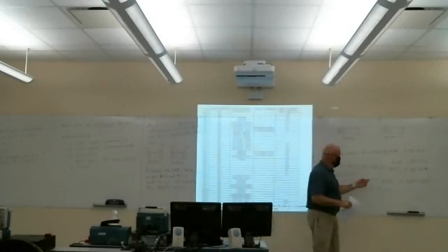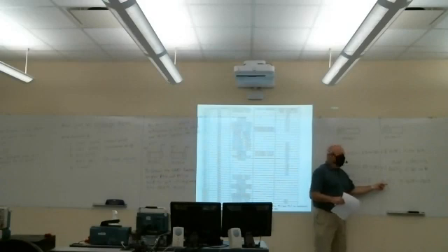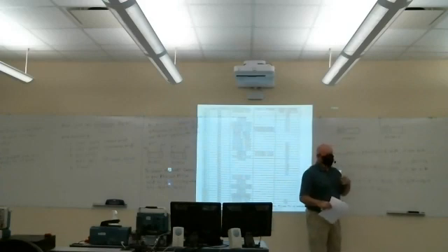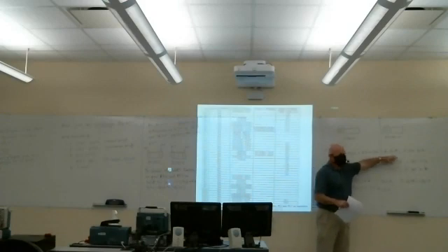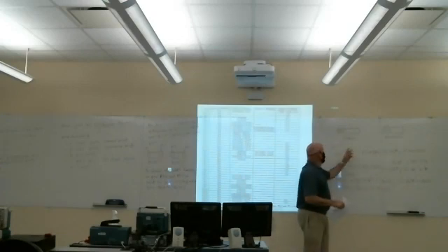So this would take the 1, 1, followed by 6 zeros and convert to 0, 0 followed by 6 ones, which is what 3F is. So not C0 is exactly the same as just writing 3F. You can certainly do it that way, but doing it this way, I don't have to worry about computing the one value corresponding to the 2 bits that I want to change.